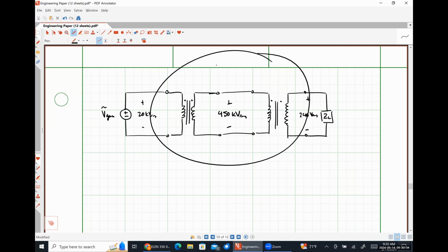These sockets right here are rated for 15 amps. I can tell that literally just by looking at it. If it had, actually, I take that back. This one is a 20 because it has a notch. So that's a 20 amp outlet. The other ones around the room without the little notch are 15 amps. There's all kinds of different things, all kinds of different ratings. I'm not super worried about the current, but if you have a high enough voltage,